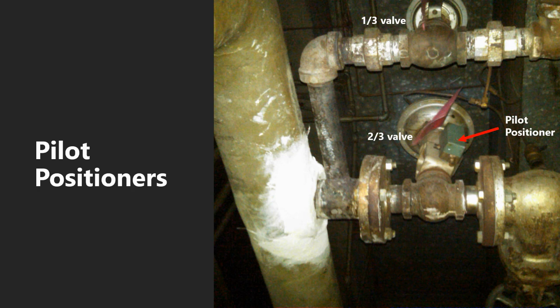First is to allow the ability to functionally shift the spring range of a valve, such as if two valves with the same spring range are to be operated in a sequential manner. For example, these two valves in the picture appear designed to operate as what's called a 1/3, 2/3 steam valve arrangement.